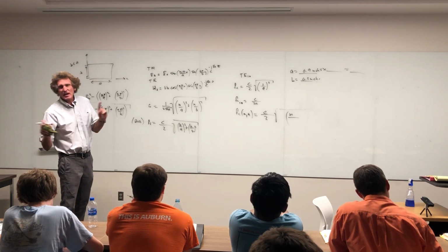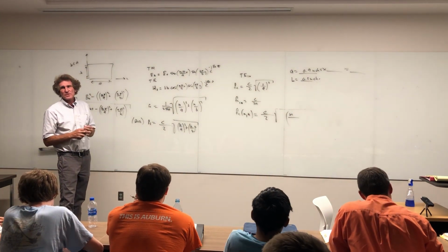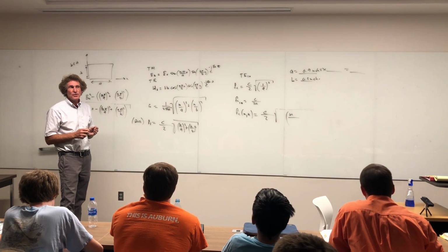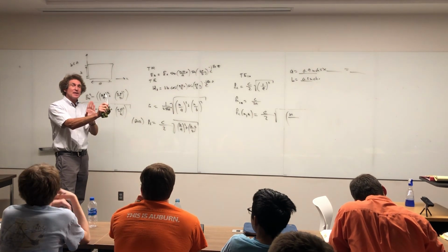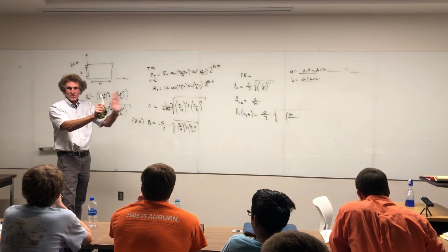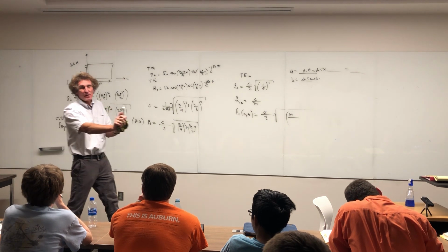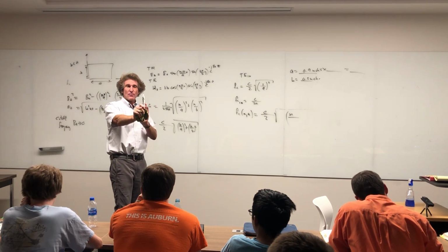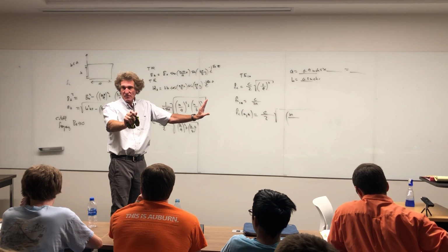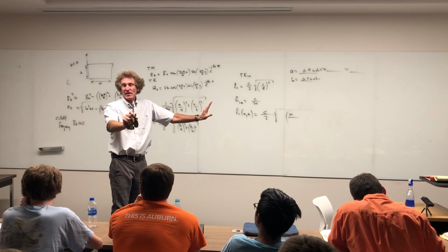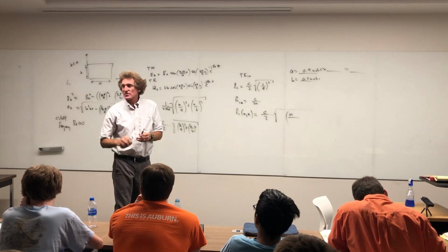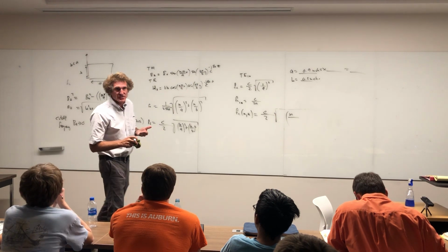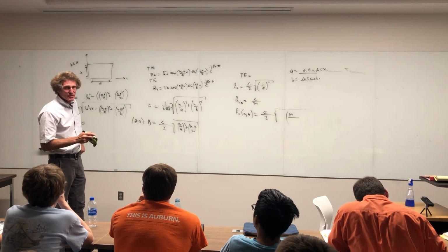The only exceptions are if I send energy at 2 different modes, but extract that energy in 2 different ports. One port pulls out energy in the 1-0 mode, 1-0 frequency, and at the 2-0 frequency I'll have a filter on, and I'll pull out energy there. And these are extreme cases. I've almost never had to do that, but that's one of the reasons possibly for doing that.